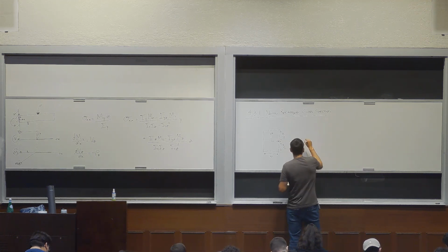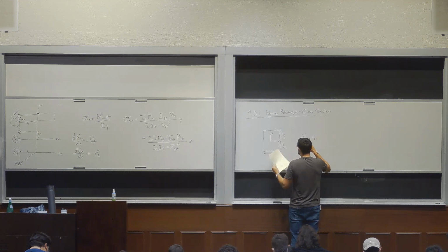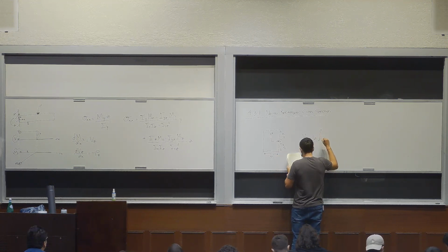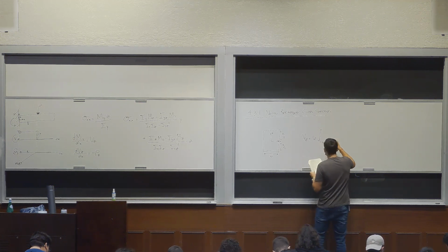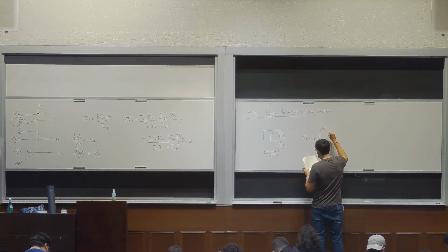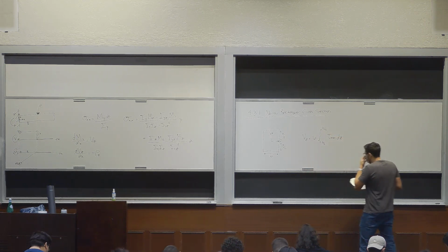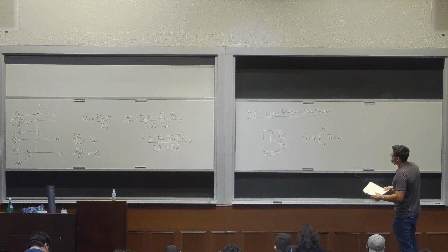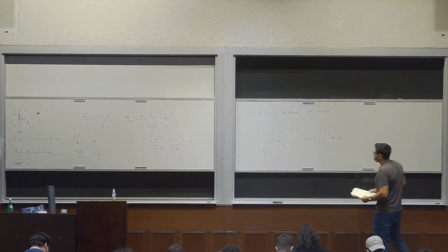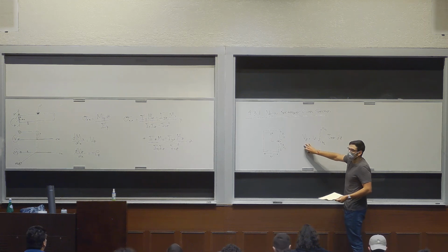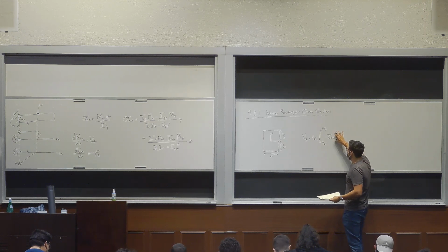And that relationship is simply Vz equals, in this case, b times the integral from negative h over 2 to h over 2 of tau xz dz. However, even if we were given this number, we wouldn't be able to derive the distribution of tau xz. So we have to find a different way.